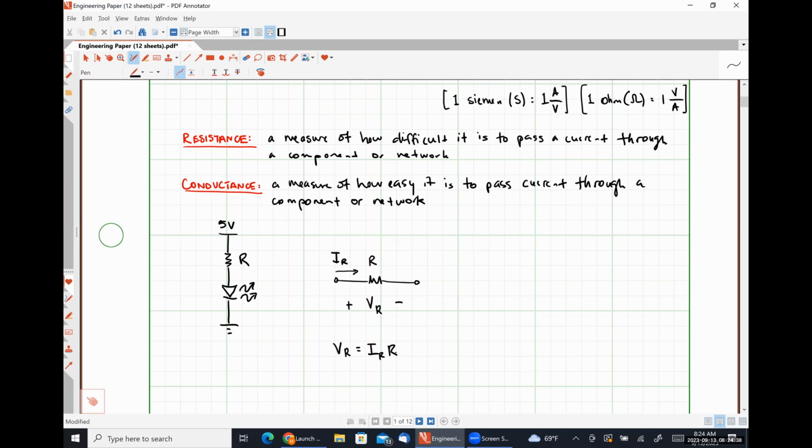And that's the Ohm's law that you guys all learned way back in your freshman class, right? V is equal to I times R. However, because we are doing that pesky thing of paying attention to polarities and trying to satisfy the passive sign convention, if instead we have a resistor R and things are set up such that the current is flowing into the negative polarity terminal, Ohm's law will now be expressed as negative I times R. And the reason why it has to be this way is because resistors can only absorb power, which means one of those two quantities, either the voltage or the current, literally has to be negative, okay? So that negative sign is fixing things so that it will be absorbing positive power, okay?